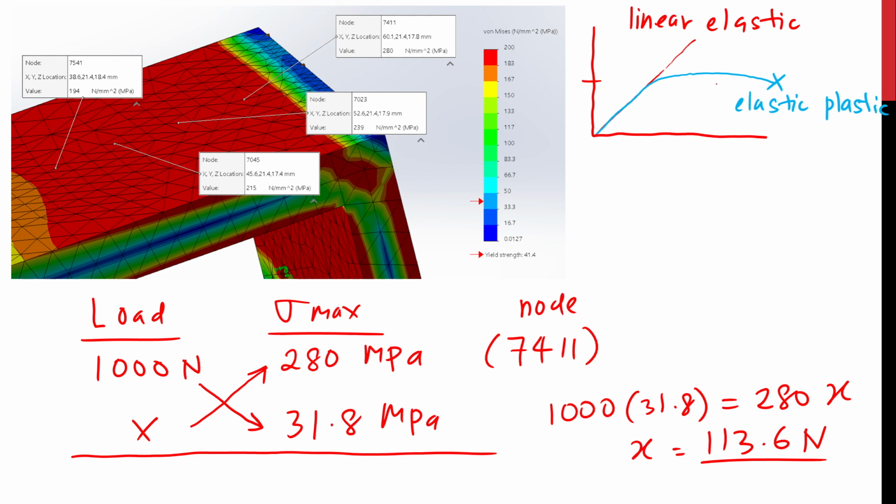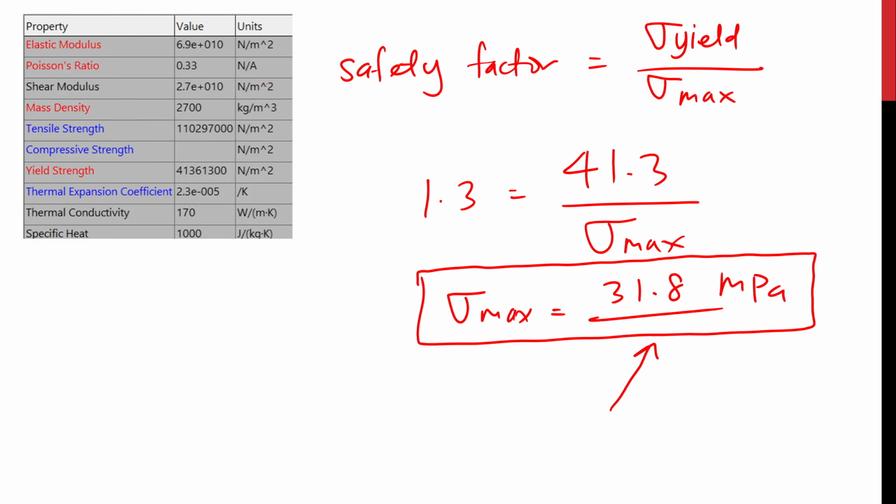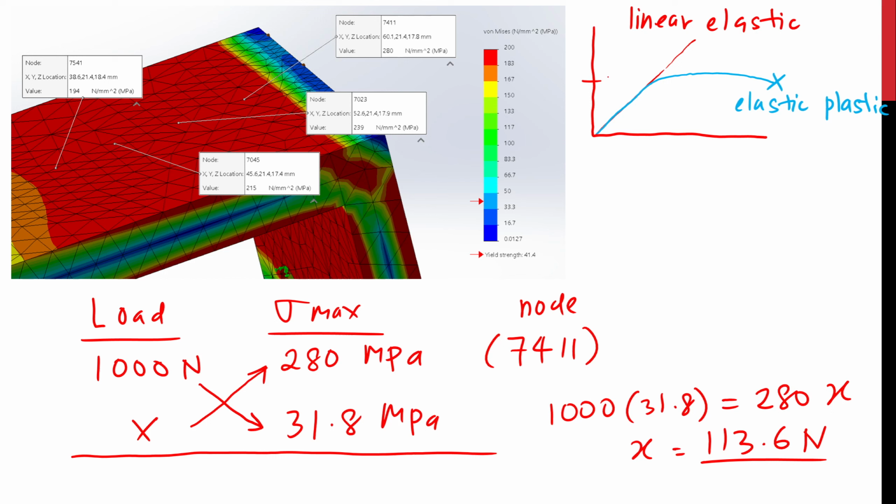Meaning, even though your tensile strength is somewhere, how much tensile strength? Tensile strength is about 110 only. So over here is about 110. But you are testing, you're getting here already, which is 280. So the material model is behaving linearly, and it's going to behave linearly until the moon, all the way straight line, because this is our material model, linear elastic.